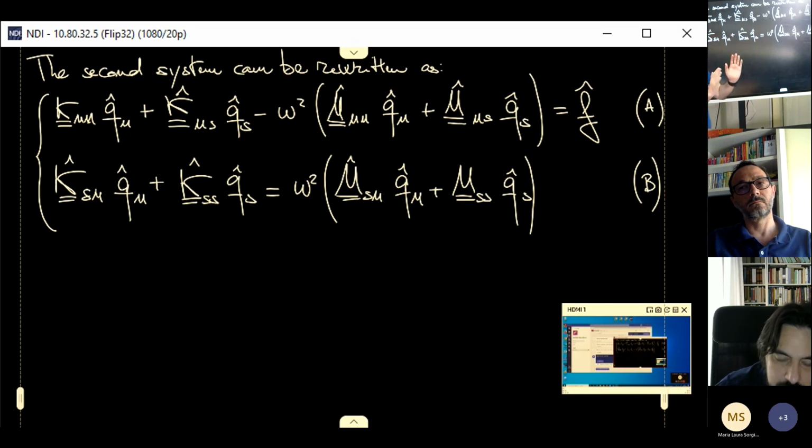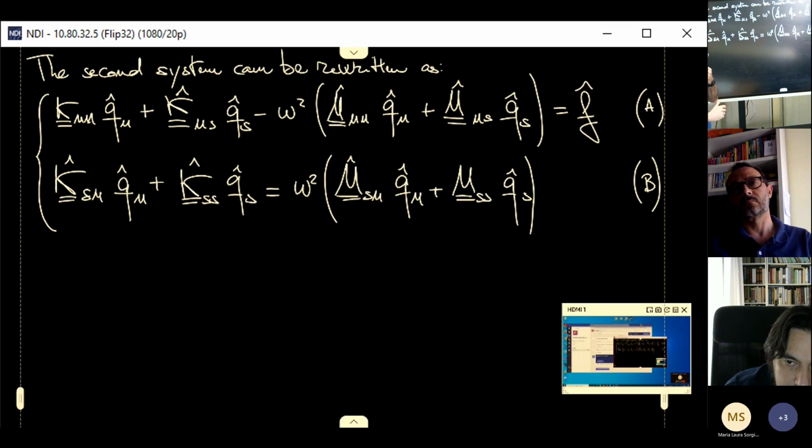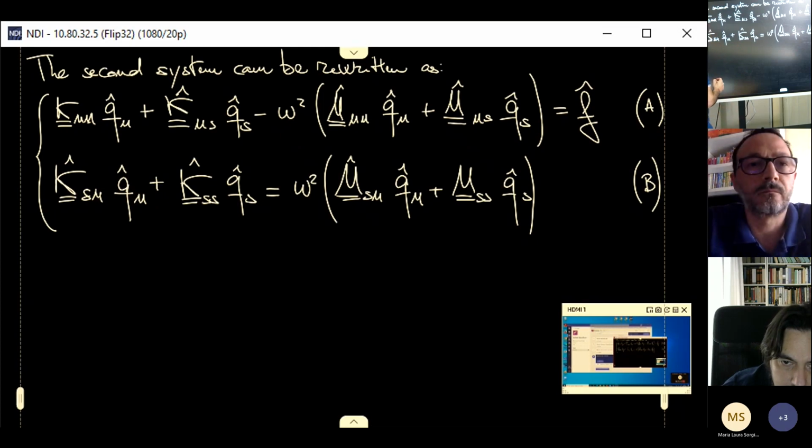Now, so this is the frame into which we are going to build our technique to reduce the number of coordinates. Okay, we have built all these frames. So the hypothesis for the use of these techniques is, first, conservation of elastic potential energy and kinetic energy. And second, the fact that there has to be no load insisting on slave nodes. If these are respected, then we can build on.